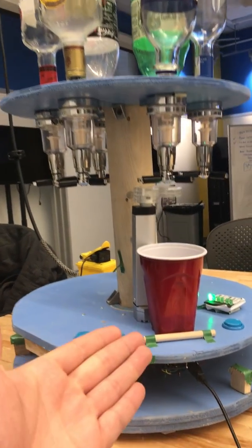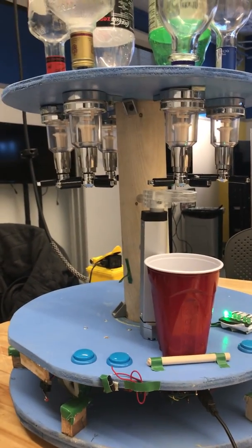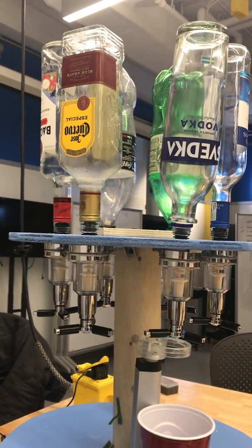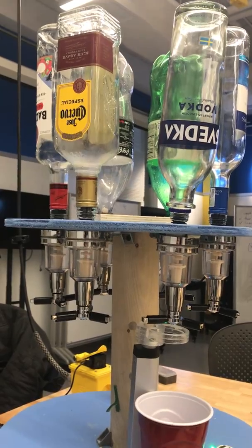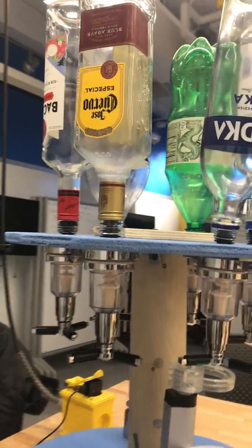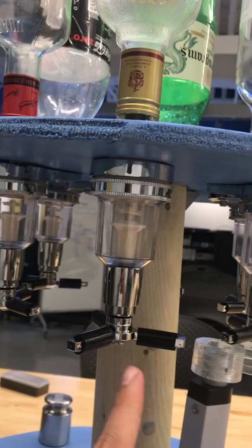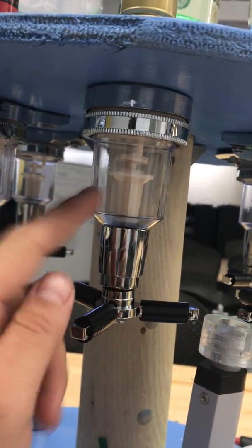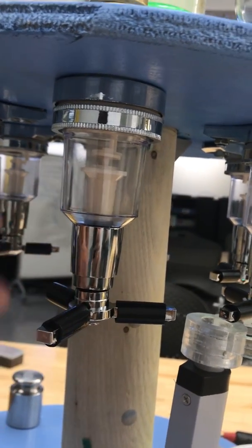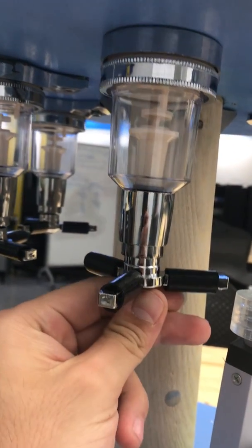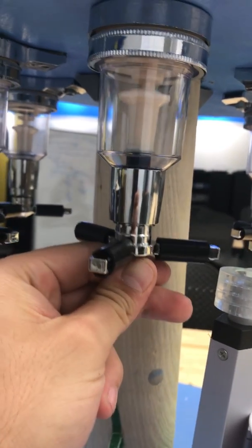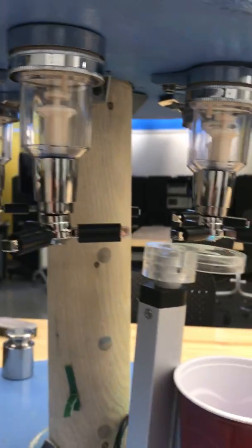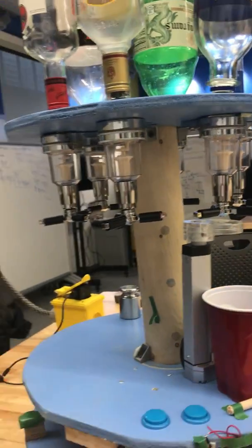As you can see, one places the cup here, and it goes around this post in order to serve the drinks for you. It houses 6 different liquids found at the top of the robot, wherein each of these liquid containers are connected to these shot pours underneath. These shot pours contain exactly 1 shot of alcohol or liquid into this container before being dispensed, once this lever has been pushed upwards. And then it only dispenses the liquid in this container and not the rest of the drink above. So this particular robot bartender allows for manual pour.